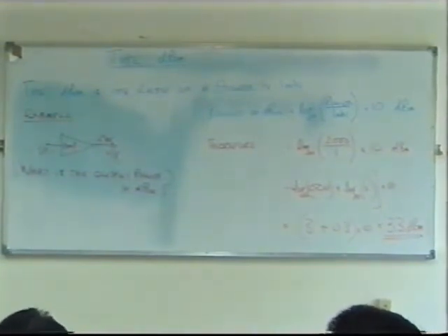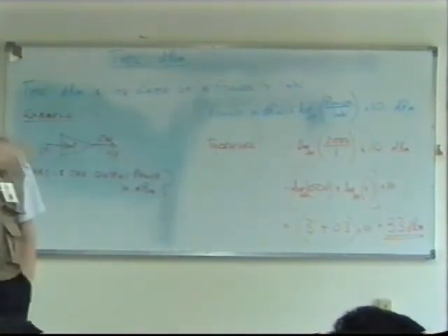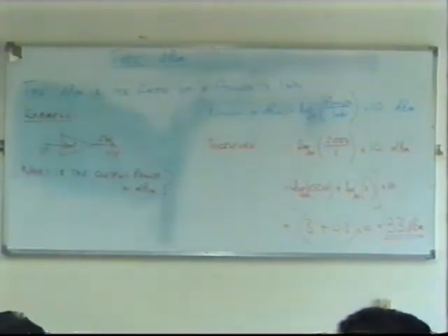What will happen if we fix this modem to more than 30 dBm? Well, in that example, probably we would start to interfere with other lines. There's a certain maximum power you can send down a telephone line because of the way the cables are together. If you put a bigger signal down, you start to interfere with other lines. Yes, what they call crosstalk. Yeah, exactly. That's right. So you've got to be careful with your modem. But you always fix it from the PTT, not from the modem. I'm assuming everything's all right on the PTT.